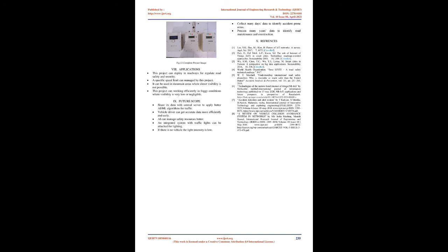G. Arduino Mega. The Arduino Mega 2560 may be a microcontroller board based on the ATmega2560. It has 54 digital input/output pins, of which 15 can be used as PWM outputs, 16 analog inputs, 4 UARTs, hardware serial ports, a 16 MHz quartz crystal oscillator, a USB connection, a power jack, an ICSP header, and a reset button. It contains everything needed to support the microcontroller. Simply connect it to a computer with a USB cable or power it with an AC to DC adapter or battery to get started.